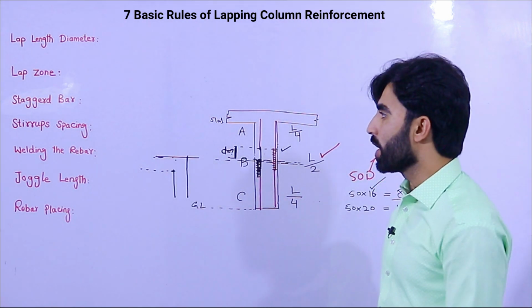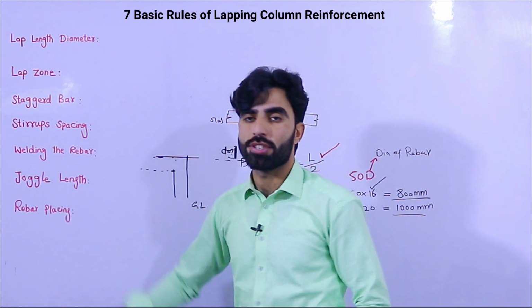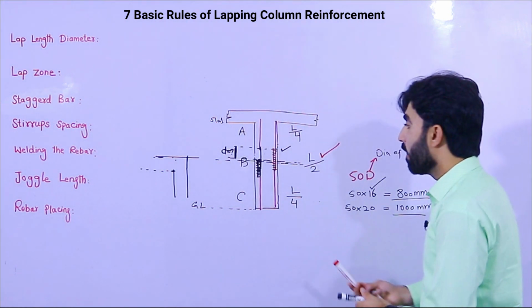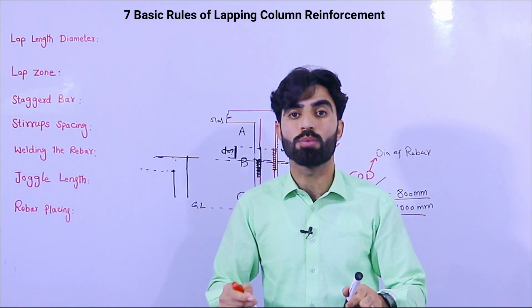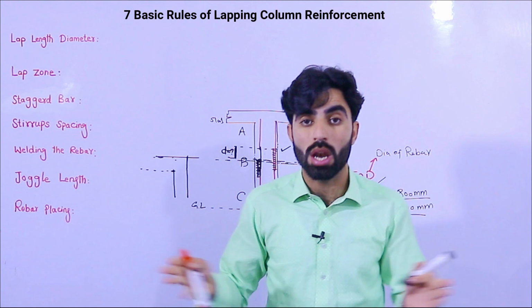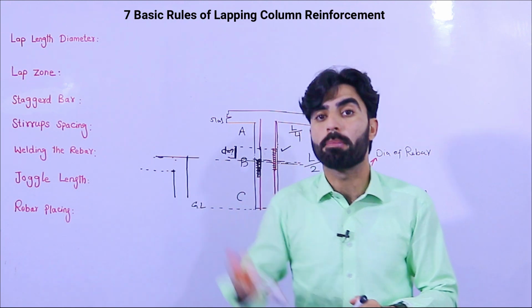Now guys, the fourth one is stirrups or tie spacing. So what should be the spacing? Remember guys, where we are providing the lapping length, on that place we should provide the stirrups or ties closely compared to the top and bottom.